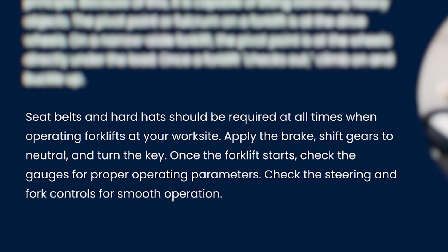Before operating, the forklift should be inspected. The operator should climb on and buckle up, apply the brake, shift to neutral, and start the truck. Once running, the gauges, steering, and fork controls should all be checked to confirm proper operation.